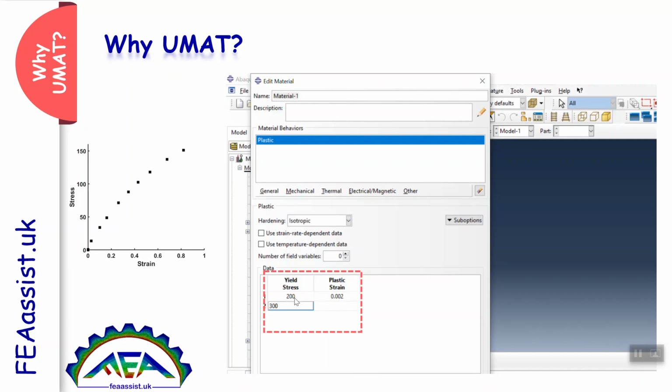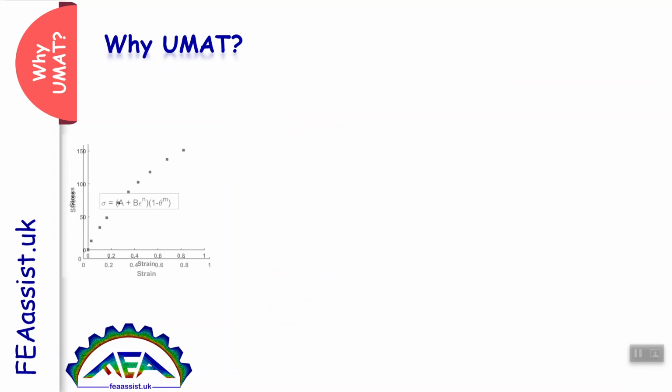This is the simplest way of solving the problem, but it is not precise because Abaqus interpolates between these points and solves the problem in all points. If you want to solve your problem more precisely, then you need to have a constitutive equation, a constitutive behavior for your material.